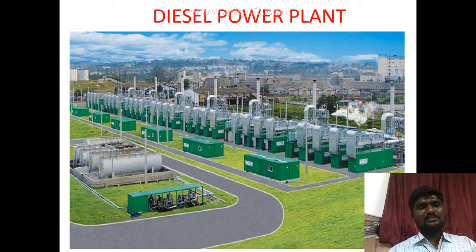The second one is mean effective pressure. What is meant by mean effective pressure? It is how much work is done and how much swept volume is developed, that is W divided by V1 minus V2. So the mean effective pressure Pm equals the area of the PV diagram divided by the length of the diagram, right? The next one is power. Power is defined as the amount of work done per unit mass flow rate of the working substance, right?